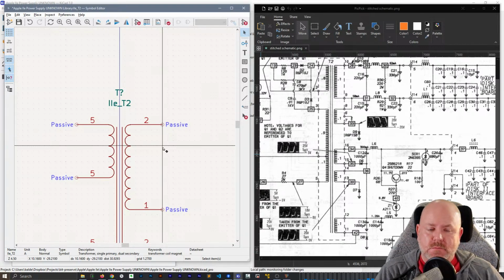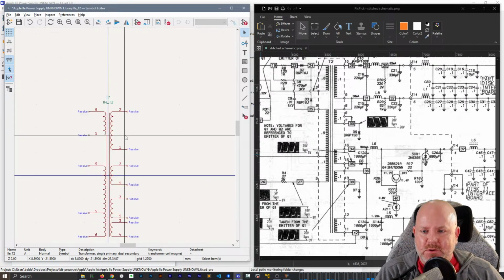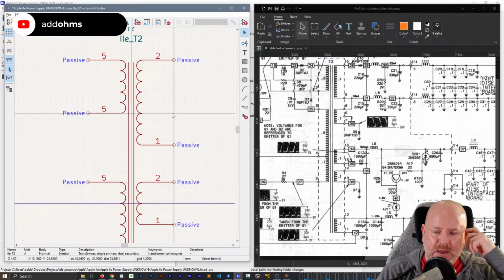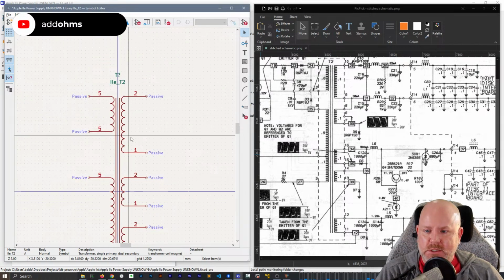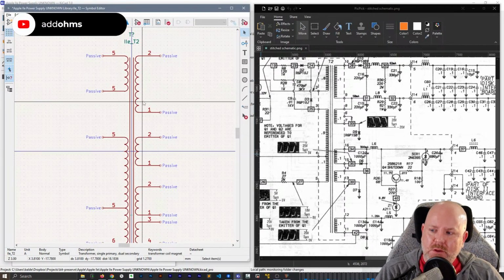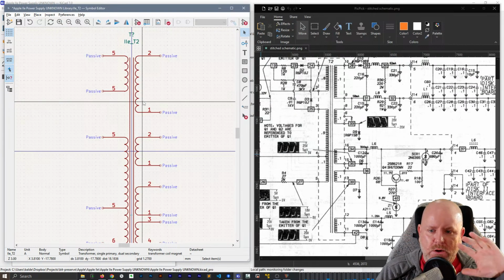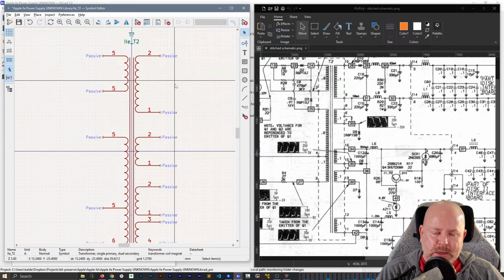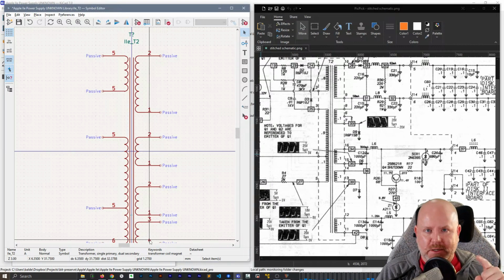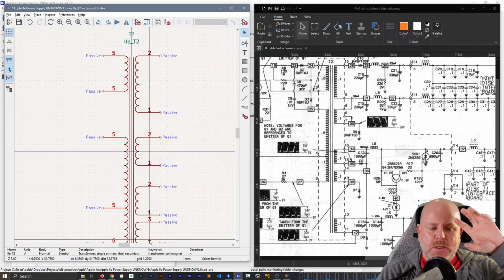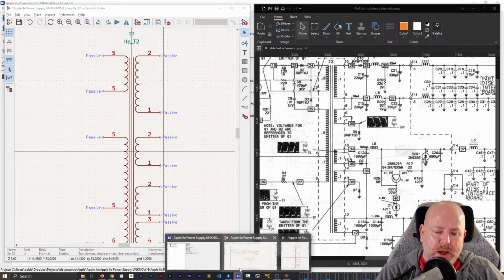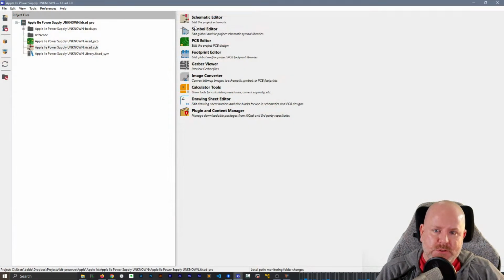Okay, Renee. It sounds like you probably have enough basic knowledge of what you need to do. What I want to point out though is in KiCad, a schematic and a footprint are two completely separate things. And it's important because if you use Eagle or maybe some others, a symbol can have both, and it gets more confusing in my opinion.